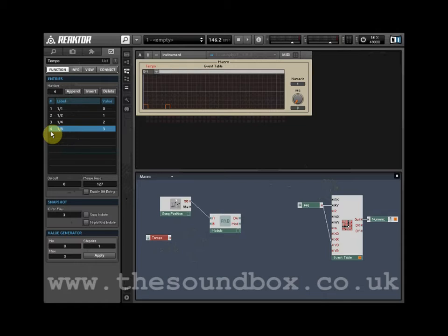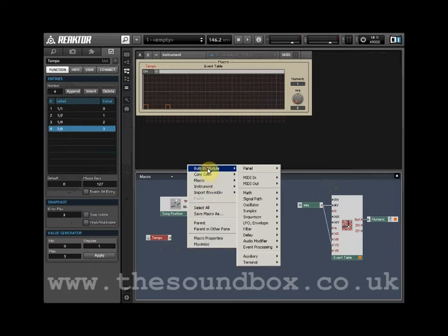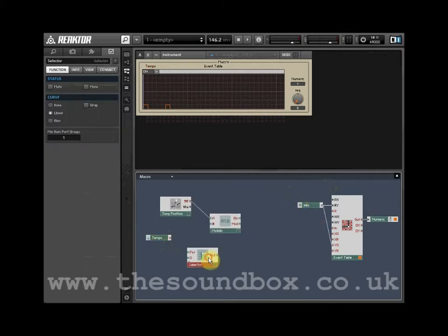In the Structure panel, right-click, select Built-in Module, select Signal Path, select Selector Scanner. This module will be used to complete the switching process. We need the same number of ports to match the number of switch positions. In the field for minimum number port groups, type 4.